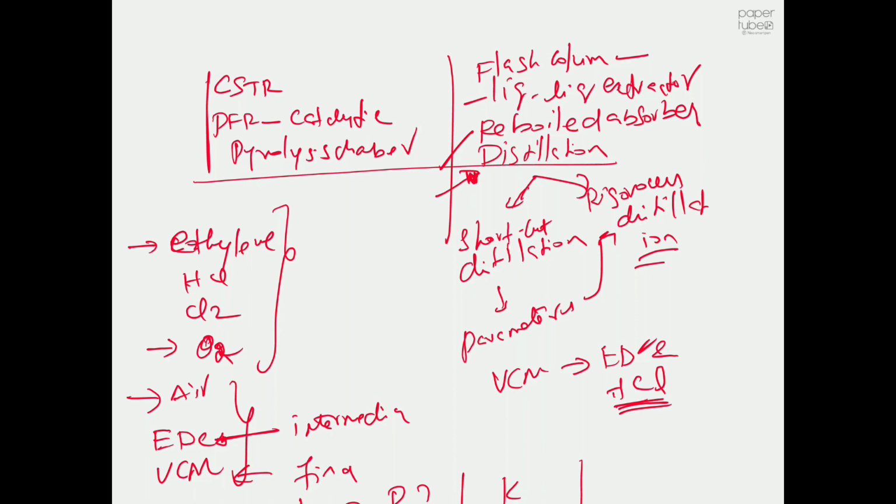Since you are a chemical engineer, it's also not a bad idea to remember these values, and then we should also maintain the condenser temperature at 25 to 49 degrees centigrade. Obviously, this is not a universal rule. If we cannot achieve the separation in this particular range, obviously we have to think about other things. Yeah, we can even use some other refrigerant in order to maintain some low temperature in the condenser. Yeah, so keep those things in mind.